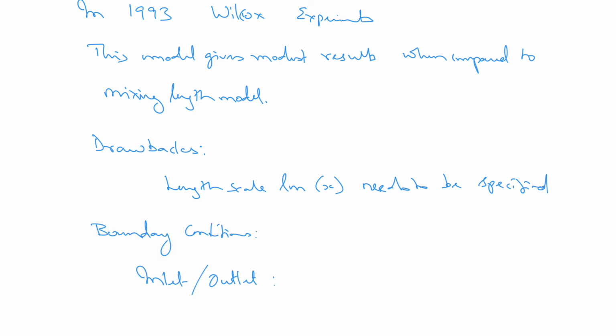If you want to supply boundary conditions when you're practically implementing these kinds of model, you need to provide the values of k in the inlet, and in outlets one might use zero gradient boundary condition to solve the governing equations. For wall boundary conditions and related boundary conditions can be applied. For other boundary conditions, one can refer to the reference books, wherein they would have specified what kind of boundary conditions you can apply when you are coming up with special boundaries.